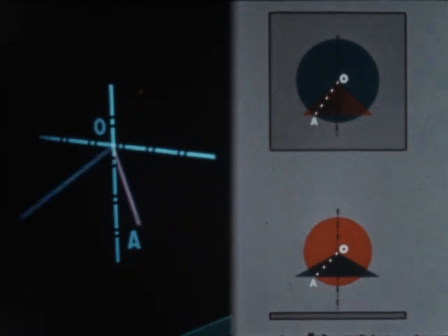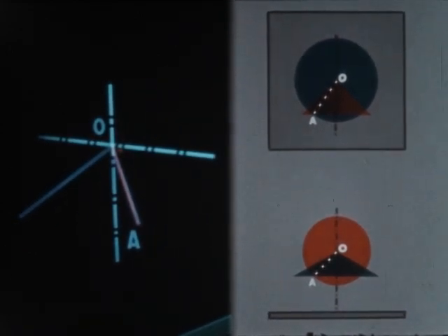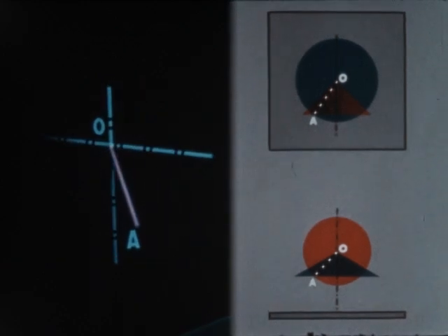The elements generating these 2 cones will coincide in 2 positions, one of which is emphasized as line AO. Since AO is common to both cones, it makes the specified angle with each of the given lines. This direction line is shown in top and front views. Note that point A is one of 2 points where the base circles intersect. It is important to remember that both of these right cones have elements of equal length.